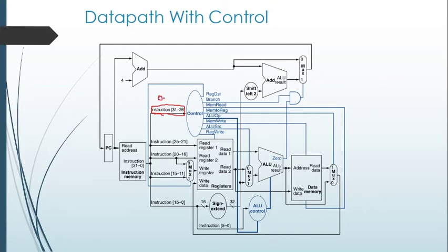So this is your opcode. I just write OP for opcode. That opcode is the input of the control unit, and it will generate all these control signals accordingly for every instruction. So this is a simple single-cycle implementation. It means all these different modules will act according to the instruction given by the opcode. So for an R type instruction, these will have different values.